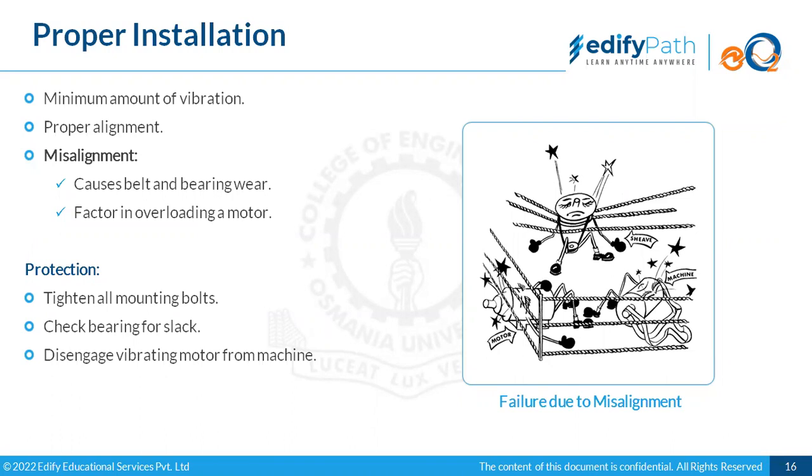We should be checking the belts through which it is driving the machine, and the proper setting of the pulleys. Even when we are taking it for overhauling and all those processes, we are ensuring that the fitment is proper when it has been reinstalled there.